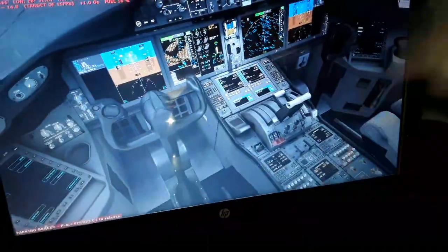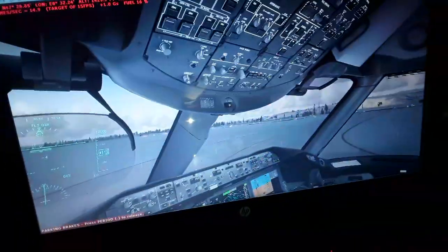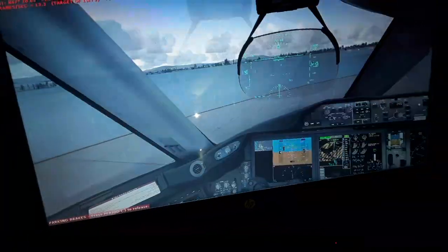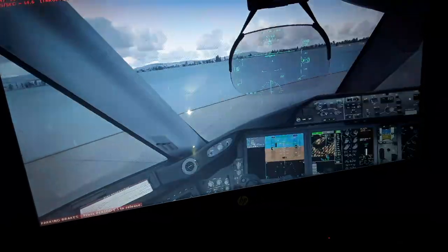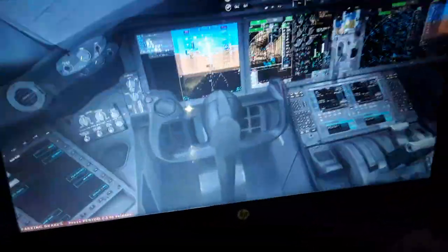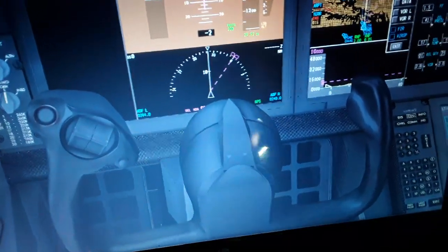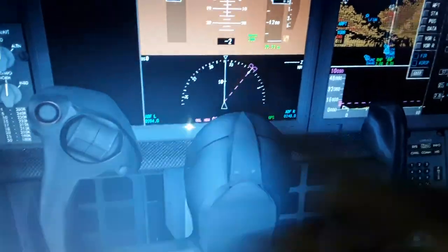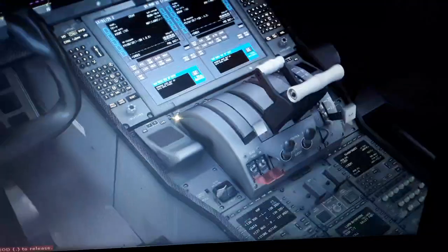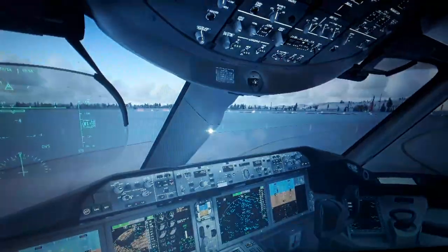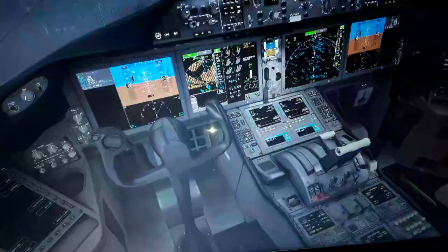So we go to the right systems now. We have here the horizontal trim stabilizer, the tail stabilizer. I'm going to show you how to trim the horizontal tail of the aircraft when you fly. You use these trim switches for the Boeing 787. Other aircraft have the trim wheel also over here, like the 737. The 787 is automated a little bit, so it doesn't need this way of trimming.